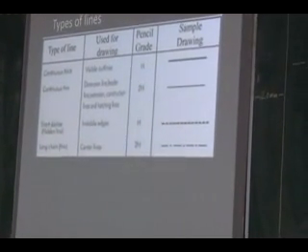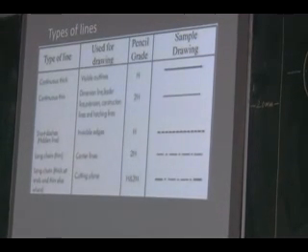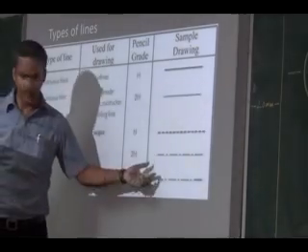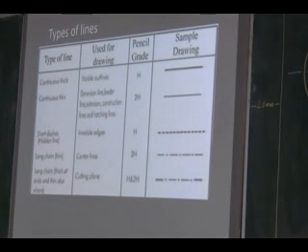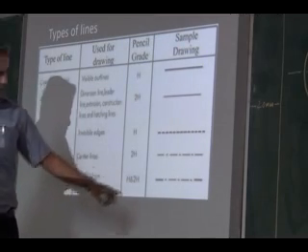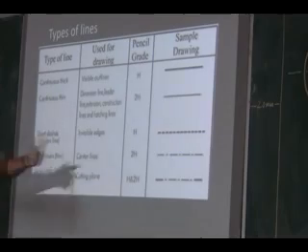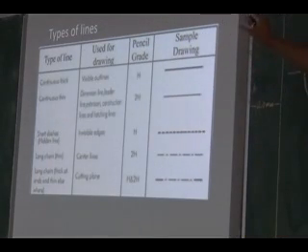Next is the long chain line, thick at the ends and thin elsewhere. Right? Typically it is similar to the center line. So what is the difference? It is thick at ends and thin elsewhere. The same center line you have to draw. The normal center line is thin all over. The last two ends you have to thicken.